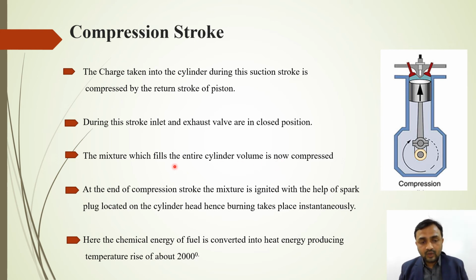Okay. Fourth one is, at the end of the compression stroke, the mixture is ignited with the help of your spark plug. After the compression ends, the air fuel mixture is ignited with the help of your spark plug, which is located on the top of the cylinder head here. Hence, burning takes place instantaneously.